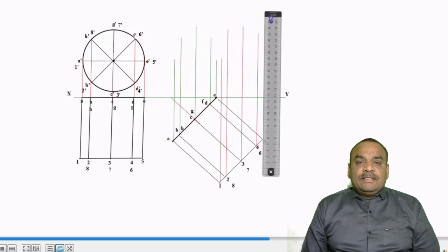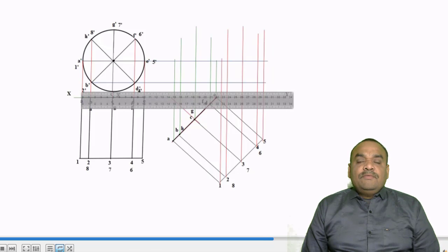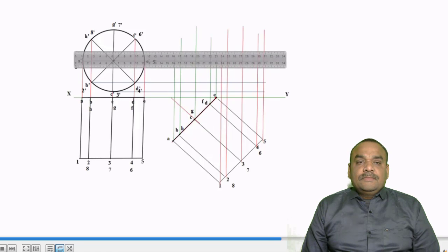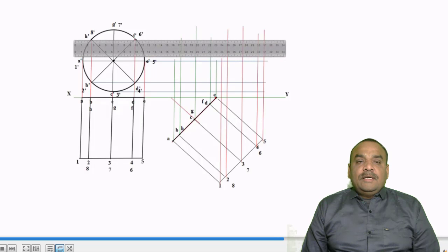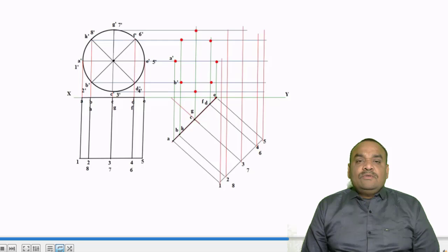So here friends, you have to check your ABCD base, it is away from the observer because your observer is here. So it is away from the observer, and this base 1, 2, 3 base is nearer to the observer. Now similarly, you can draw the projection from the first stage elevation, and all projections should be parallel to the XY line. So this is a projection from HF, and all the projections, horizontal and vertical, intersect each other, where you can mark your appropriate points.